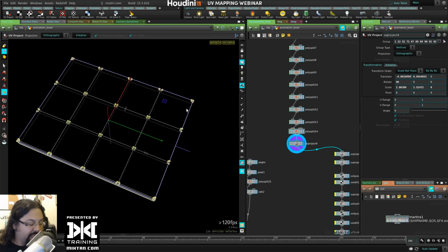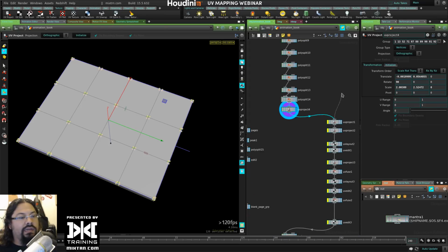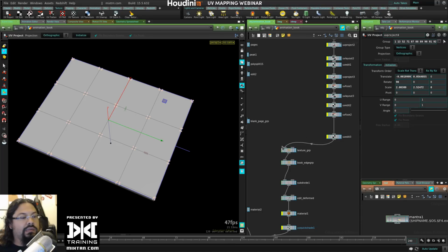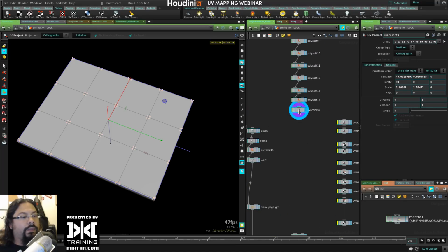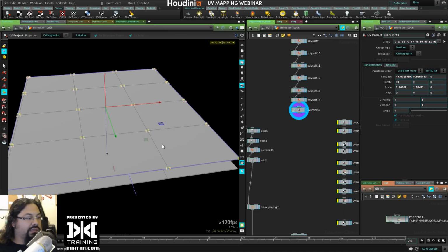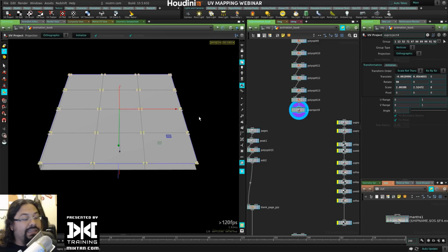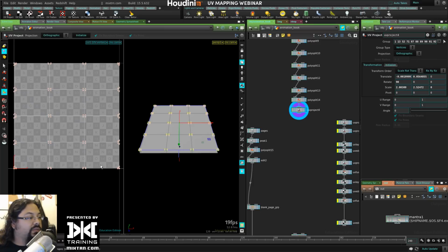That's the UV projection. UV, yeah, exactly, the UV projection that we have there. And what's happening here, save this, save it over. What's happening here is just filling that projection with that selection that we had, which just means it translates, rotates, and scales that projection to fill the whole texture space here.